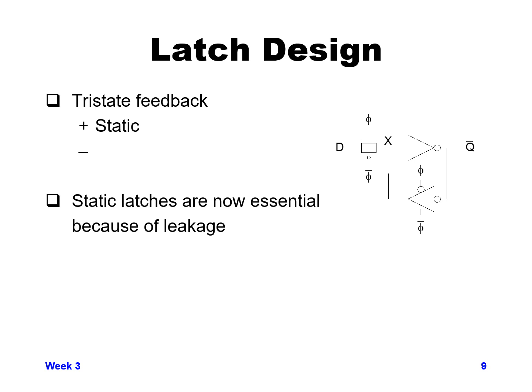So holding state dynamically can be dangerous if you do it for too long; you can only do it for a short period of time. Because there's active feedback with that tri-state feedback, this gives a static value that will stay there over time, and you can wait pretty much as long as you want, as long as voltage and power are being supplied to your circuit, and it will keep that same value.